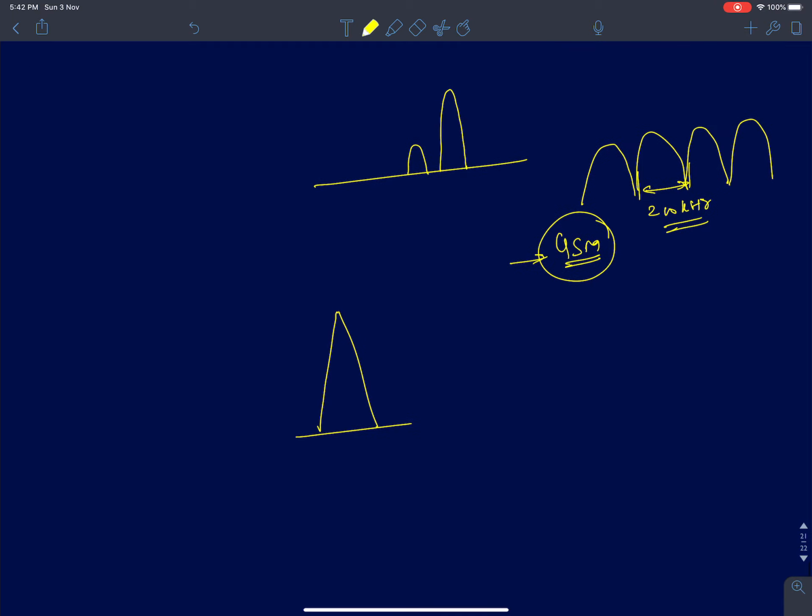Say from the tower you have a receiver here, which is your cell phone, and there is also another cell phone close by. Your receiver is supposed to expect a signal at frequency f1 from the cell tower, and the adjacent cell phone is transmitting at a frequency closer to your own frequency. This is a wireless world, so you will start receiving any signal that's available in the air. Therefore you will receive both f1 and f2, and f2 can be much stronger than your intended signal.